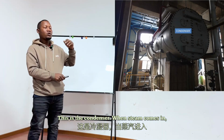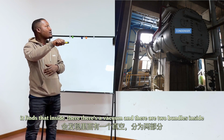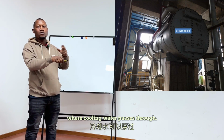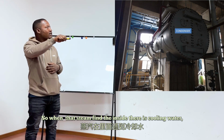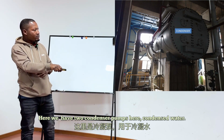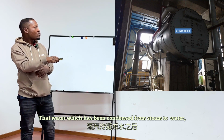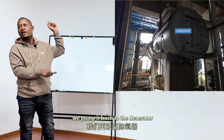This is the condenser. When steam comes in, inside there's a vacuum, and there are 2 bundles inside where cooling water passes through. So when the steam finds the cooling water inside, that steam is condensed into water. Here we have 2 condenser pumps for the condensed water. That water which has been condensed from steam to water, we pump it back to the deaerator.